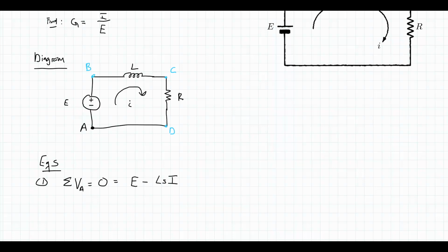So to go from C to A and then close my loop, I have to go across a resistor R. Once again, I am going with current as I go from C to A. So I'm going to have a voltage drop. So that will be a minus R times the current through it. Well, that's also I. And now I've arrived back at point A. I've closed my loop. So by KVL, it must be true that these three things sum to 0.